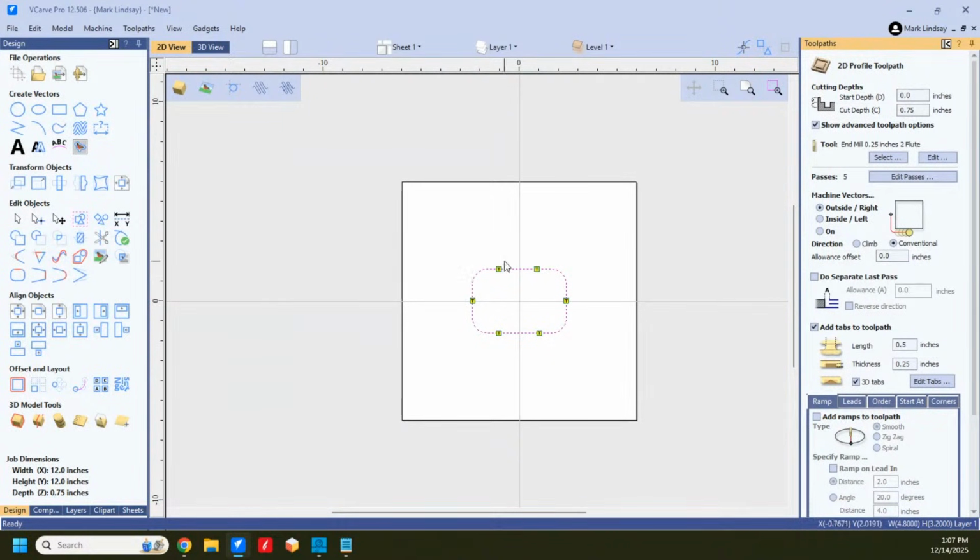So your X and Y never stop moving, but it will slow down to whatever the plunge rate for that bit is. Because again, the machine only moves at the speed of the slowest axis, which is almost always the Z.